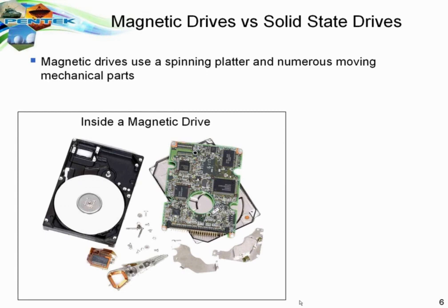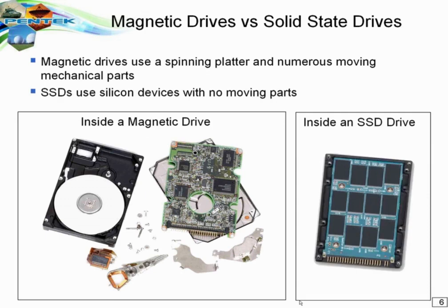Let's take a look at the system flow. How do we actually move data through the system? Well, we start out with a high-speed A to D or D to A module that has a DMA controller connected to it, and we have a RAID controller connecting, again through a DMA channel, to the solid-state or magnetic disks over SATA links.